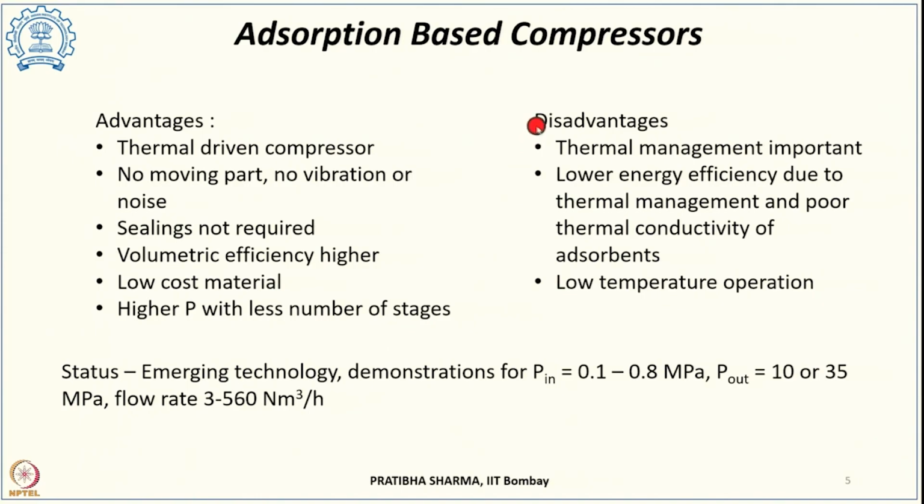But the major disadvantage of these devices is that thermal management becomes very essential, and we need to consider both the heat removal as well as the heat supply mechanism so as to have a uniform bed temperature. There is lower efficiency if there is poor thermal management, which is also associated with the poor thermal conductivity of the adsorbents used in the compressor. And we require low temperature operation, which adds to the cost and reduces efficiency.